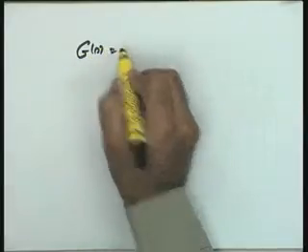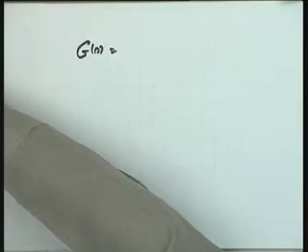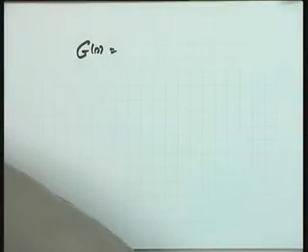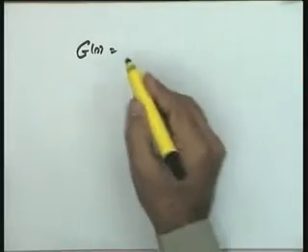So let me go towards softer plants. By softer plants I mean with respect to stability, type 1 or type 0. So there is a scope of adding a phase lag compensator to type 1 or type 0 plants. Let me take an example of type 1, because type 0 plants are more easy to control. So if we are able to discuss with respect to type 1, any example of type 0 you will be able to handle very nicely.